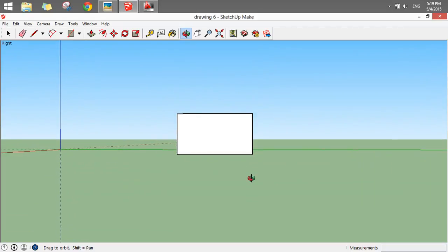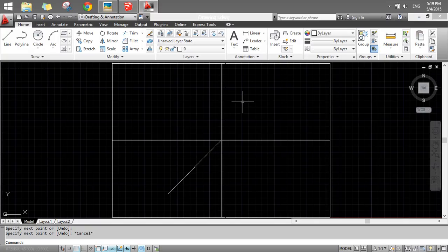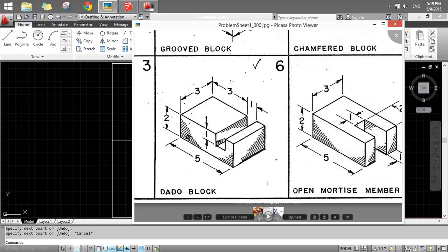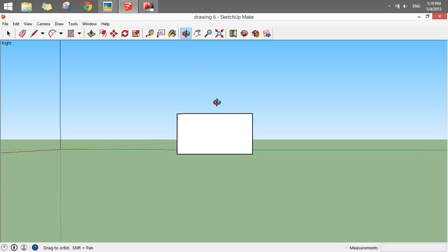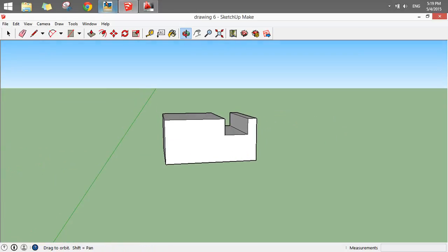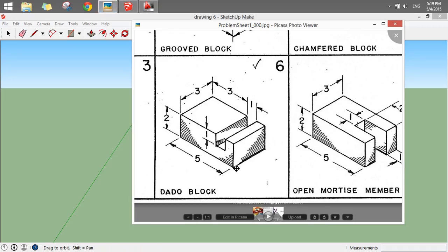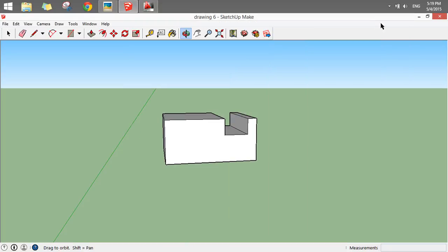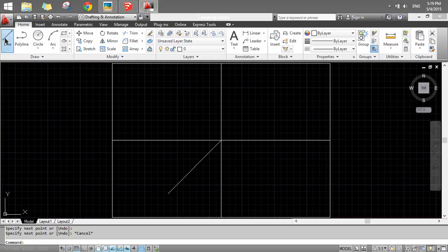its front view. So to begin with, open the reference sheet and see, in the side view, like this is the side view. This is of length 5 cm, height 2, breadth 3, with a cut junction at about 1 unit each at this corner. So drawing it, line,